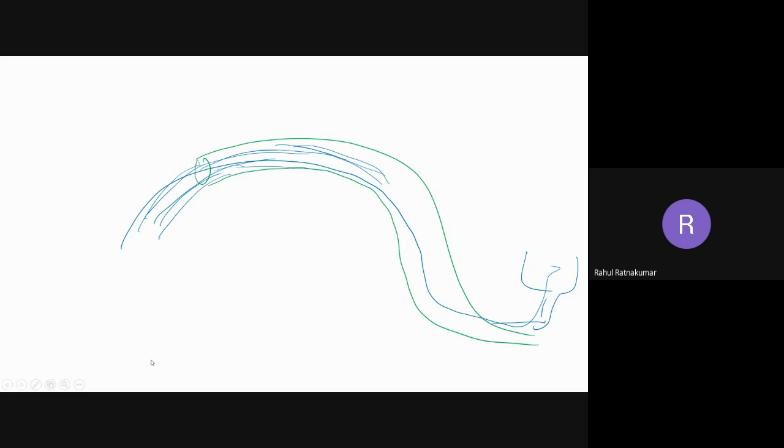So what happens when we squeeze the pipe? We can squeeze the pipe at a point here, applying some pressure with our hand. What happens? The channel is going to reduce. So the current flow is going to reduce because the channel area is going to reduce. This is the best example for the JFET. We are trying to reduce the channel or the flow of water or current here. Because of the squeezing or pressure or voltage applied, my current is going to reduce.